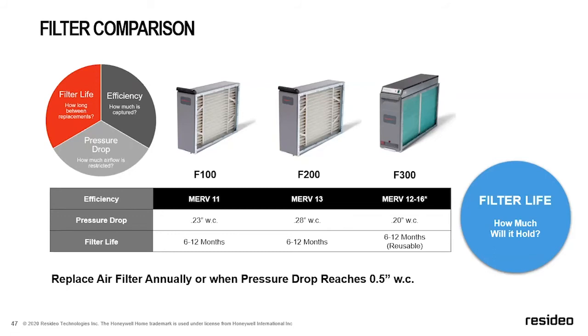All these filters are designed to last 6 to 12 months, depending on the application, what the activity level is within the home. But ultimately, if you measure a 1/2 inch static pressure drop across the filter, it's time to change it out.